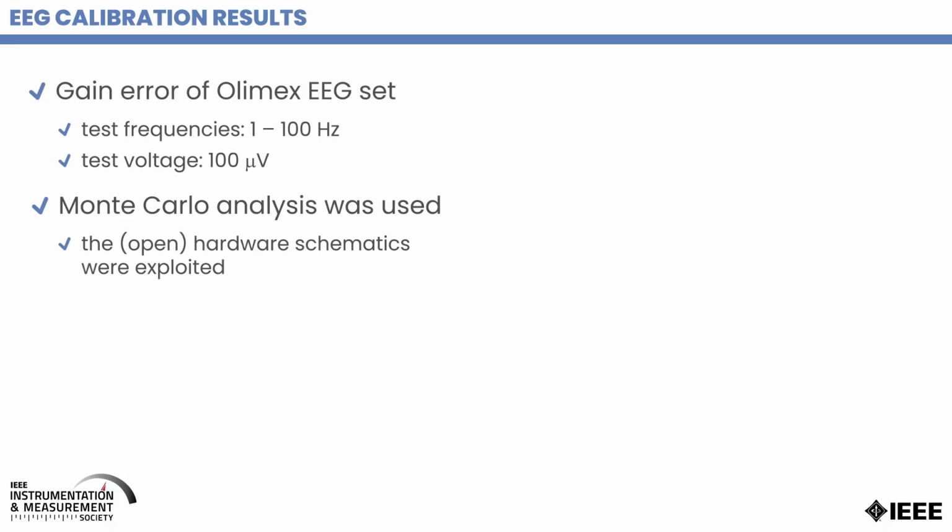The second result that we can already see from here is that, with respect to the ideal line that would have unitary gain and zero offset, this has an offset error. So these are linear errors that can be taken into account, but the fact that there were no nonlinearities was already excluding the generation, at least a significant generation, of the unexpected harmonics. We went on thus to characterize the gain. This time the setting changed because we explored different frequencies, but just one test voltage.